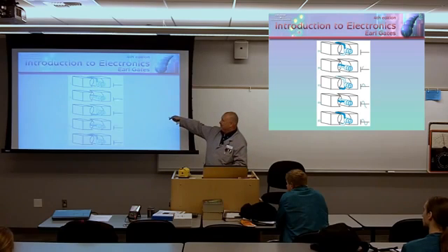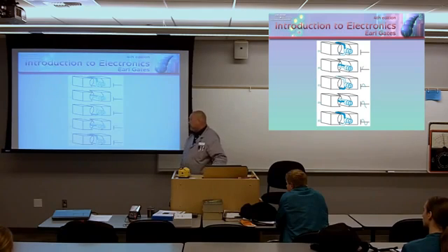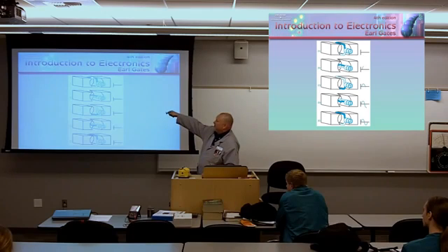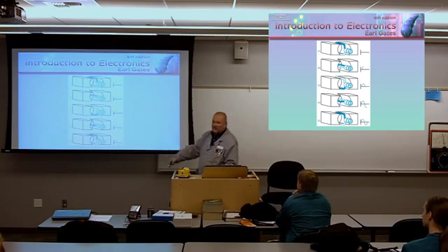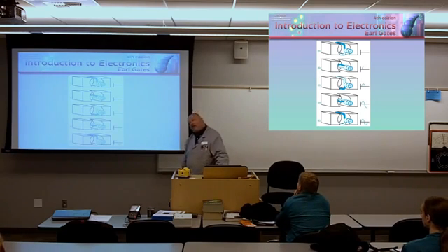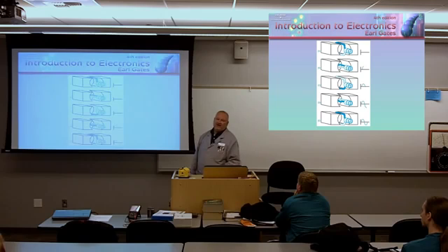Well, look what we did. When we rotated it 90 degrees, now I'm at my maximum peak value. When I rotate my armature another 90 degrees, see how I started out here at the top? Then I rotated it 90. Now I rotate it another 90, so I'm actually 180 degrees from where I started off. Am I parallel or perpendicular to the lines of flux? Parallel. What does Faraday's law say? 0. What am I generating? 0.